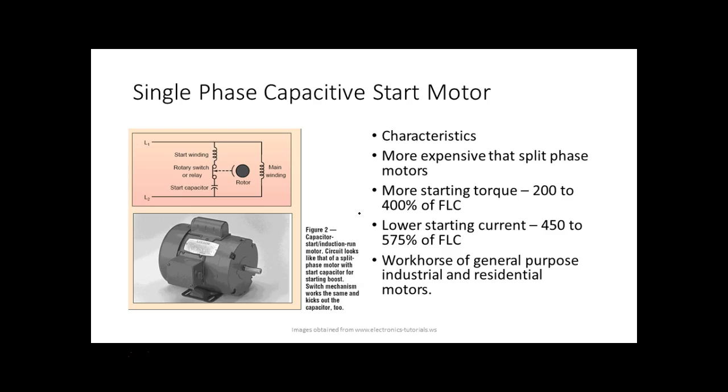On the air conditioning system, the capacitors are outside, so they go bad so many times that they'll mount the capacitor outside. So the two brown windings that you see on the stator, that's your start capacitor. So on an HVAC system, that capacitor is not going to be on the motor, it's going to be outside. And normally you can just pop the top and change that thing out pretty fast.